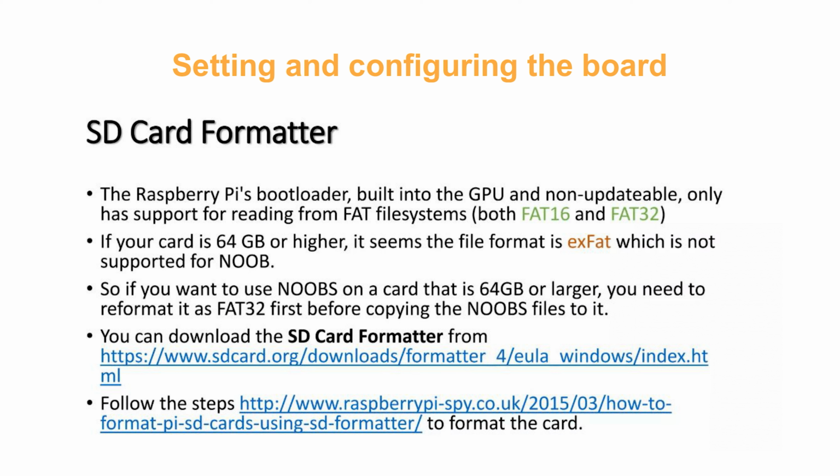First of all, the SD card formatter is needed before installing and imaging the OS. First we need to format all the files that are inbuilt in the SD card. The minimum SD card capacity is 4 GB. A 4 GB card supports Raspberry Pi B+, Raspberry Pi 2 model and Raspberry Pi 0.